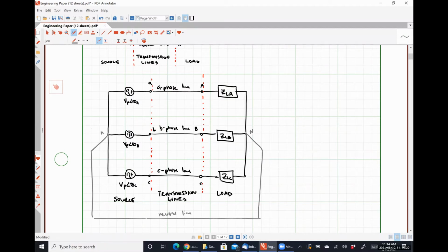If we have a system that includes the neutral line, we're still delivering 3 times as much power with only twice as much wire. Right? Yeah. So we are still at a cost advantage there. So that's the main reason that 3-phase power is used really everywhere that we want long-range transmission of electric power.